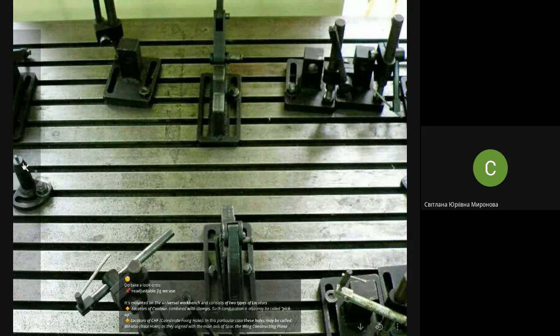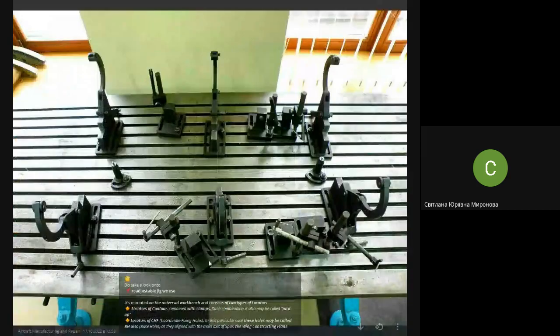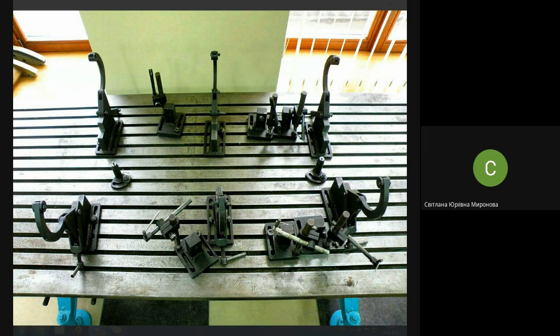A platform with a pin, and this platform is placed in a particular place here. How it appears that they align it is another story, at the end of the lab. They are aligned onto one axis, and all these locators are placed at the proper places with respect to this basic axis. Altogether, this set of locators provides accuracy of locating of spar parts.